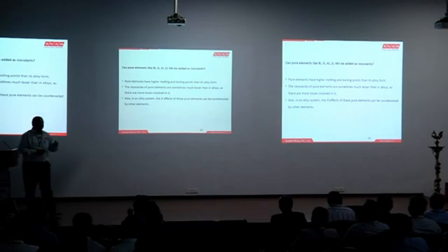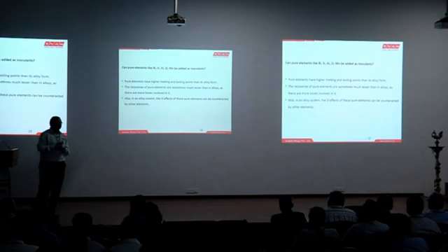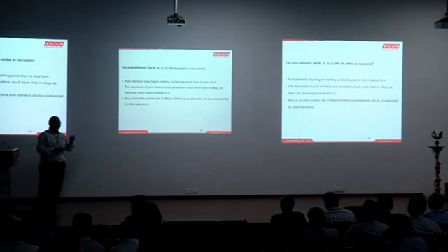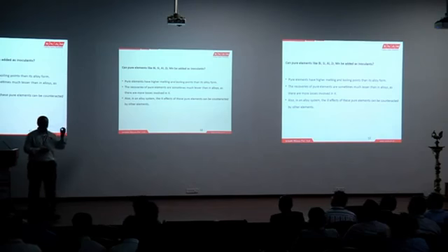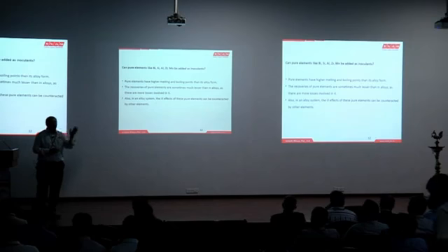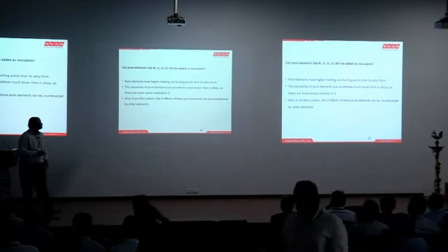See, for example, bismuth, or in ductile iron production there is an element called magnesium, the most important element being used. Magnesium is basically a carbide promoter. The moment you add magnesium, it kills the metal completely, at whatever level, say 0.4, 0.2, 0.3, 0.8 or even 0.1. That is the reason there is a demand for high inoculation levels in ductile iron foundries compared to grey cast iron foundries. It is because magnesium is added. We cannot run the foundry without magnesium or an element close to magnesium, like cerium or lanthanum.